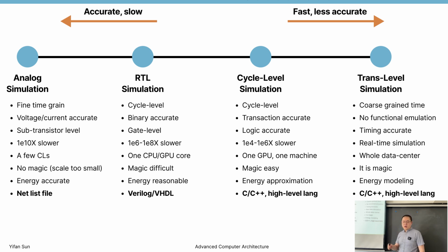consists of 2 parts. One is the static energy. It's basically what your whole chip is consuming even if you're not running anything. Then the other side is the dynamic energy. Dynamic energy happens when a transistor is flipping from a closed to open state. Whenever you flip, you consume some energy.